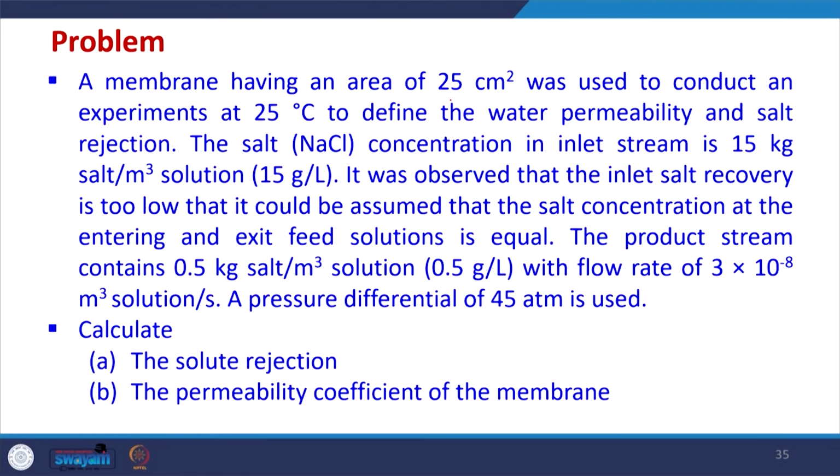Now, we will try to solve one problem before ending this particular section. This problem can be understood in a number of ways as we have discussed here, but still we will try to solve it. A membrane having an area of 25 centimeter square was used to conduct an experiment at 25 degree centigrade to find out the water permeability and salt rejection. The initial concentration in the inlet stream was 15 kg salt per meter cube, equivalent to 15 gram per liter. It was observed that the recovery is too low, so it could be assumed that the salt concentration at the entering and exit feed